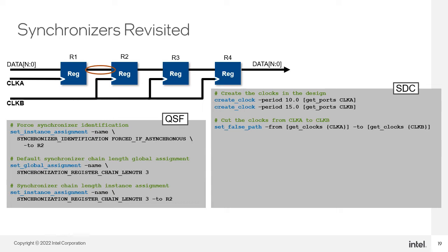The set_false_path SDC command tells Timing Analyzer, and subsequently the fitter, not to consider the paths between those two clock domains. The fitter can make the paths as long or short as it needs to. This can cause skew problems with the bus, given that one bit of a bus can be captured by the clock edge before another bit of the bus arrives for the same clock edge. The set_max_skew SDC command is the constraint you need for such a situation, but set_false_path negates a set_max_skew constraint placed on a bus.